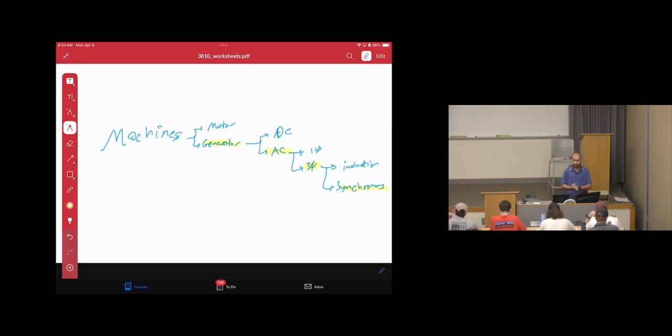three-phase synchronous generator. Why synchronous? Synchronous because it's suitable for constant speed, constant frequency. Our grid frequency is 60 hertz, then synchronous is better. Why three-phase? Because the power lines are based on three-phase. Why AC? The power is based on AC. And generator, of course, to convert mechanical energy into electrical energy. Okay? That's the reason why this is the most common.